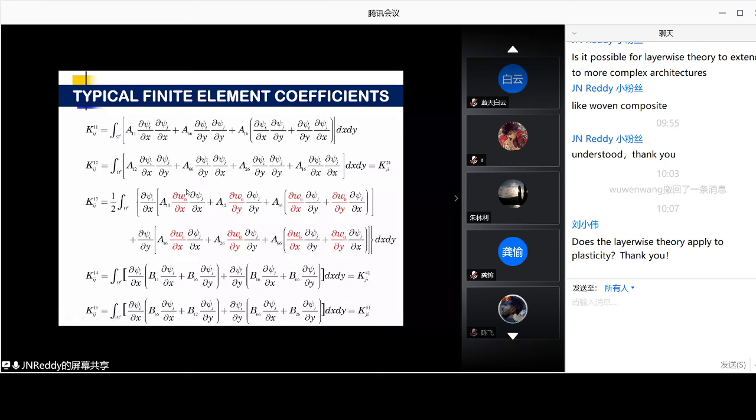I don't want you to read into anything here, but I just tried to highlight that there are nonlinear parts which are shown in red. So the K matrices depend upon unknowns. So we have to necessarily solve numerically and evaluate the K matrices numerically. Because at each iteration, we assume the deflections are known from the previous iteration, so that we can calculate the nonlinear terms based on the solution we know from the previous iteration.